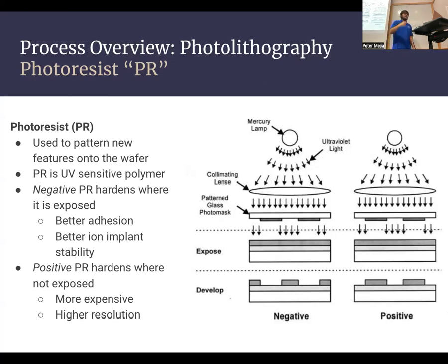And so you're going to put it in this photolithography machine, and you're going to set your exposure time, and there's some calculation to do based on the intensity of that light that day, because it changes with the day. The equipment is a little bit old, but you can just do a simple calculation and figure out how long you want to expose it for to get the exact exposure that you want. Make sure it gets through the entire layer.